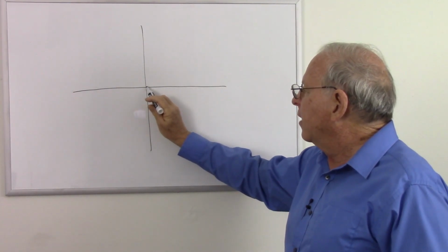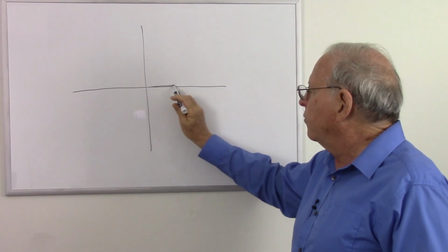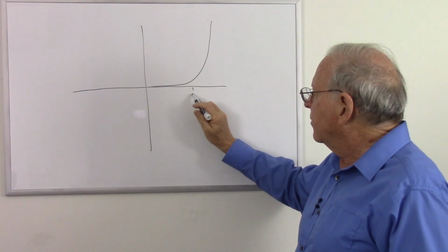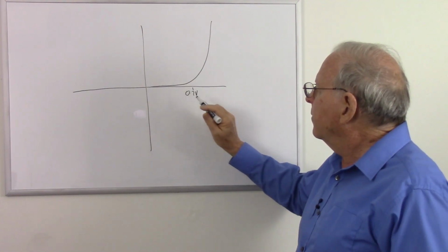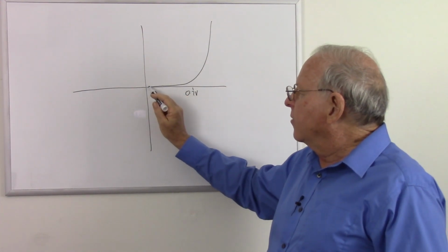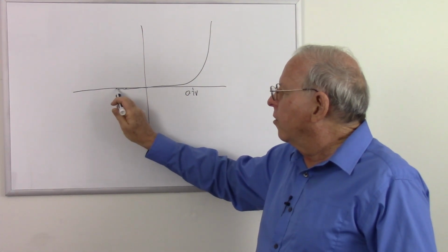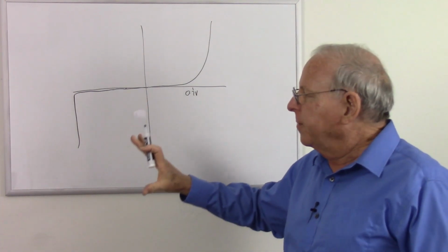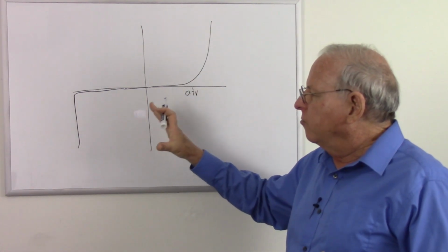I'm going to go ahead and draw that just because it will be useful. So there's your standard diode curve. I'll put that at about 0.7 volts. And then reverse bias, the normal diode is going to have almost no current, and then it's going to reach the breakdown voltage and suddenly a lot of current, and that's probably going to destroy the diode.